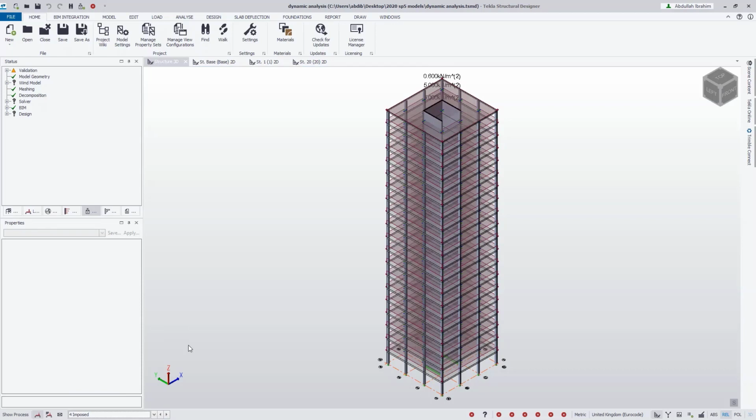So the difference between using the dynamic analysis, the wind tunnel method that I'm showing now, and the previous method, which I'll demonstrate first, is that the previous method was a very straightforward process. The way to do that would be to firstly build your model and apply the load. Make sure your model's correct and it's stable before performing a vibration analysis.